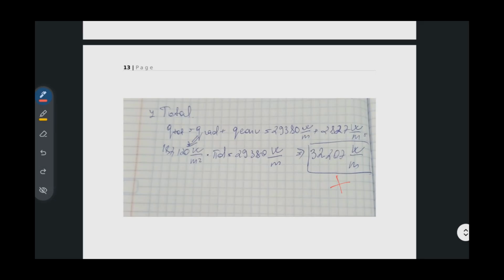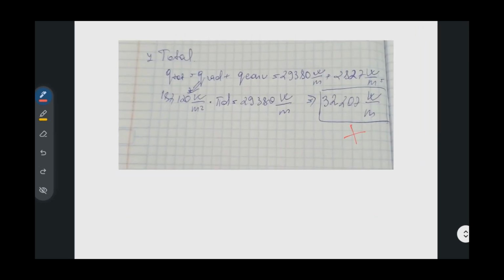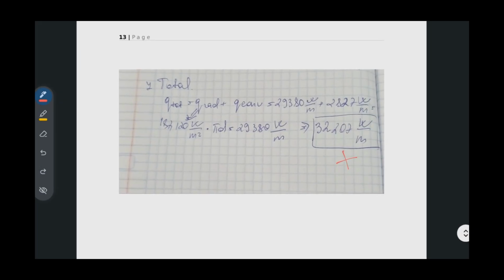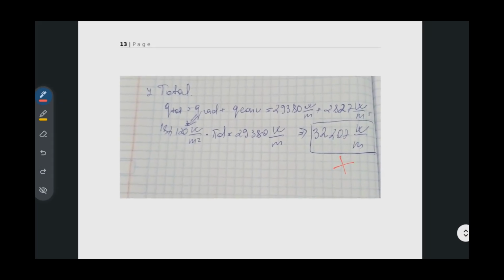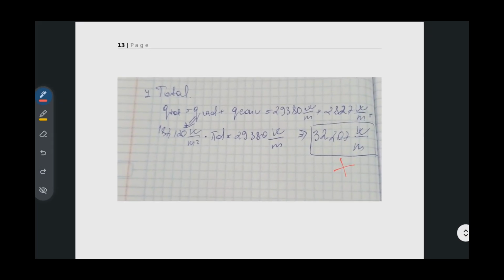For the pumps, we talked about the design procedure in general, what kind of parameters you need to know, and what kind of pump problems we mainly expect during operation, which was the cavitation. And we said that simply to avoid cavitation, you need to control your NPSH available, net positive suction head. And for the net positive suction head, we discussed the parameters that have been used in the equation.